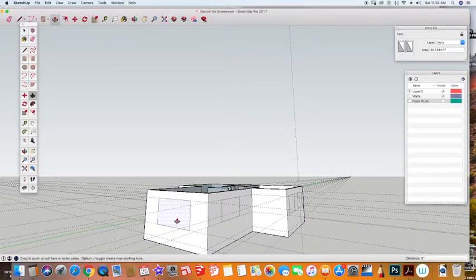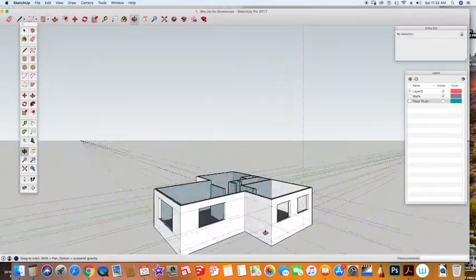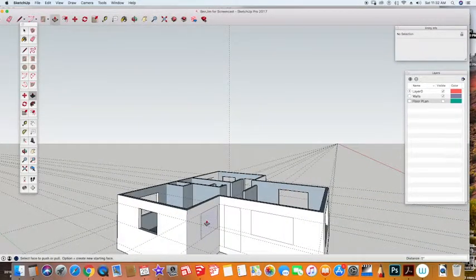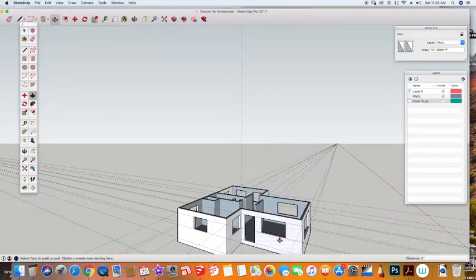So now we're going to push and pull these all in. I'm going to highlight, use the push-pull tool, highlight over it, start to push it in, and instead of pushing it all the way through, I'd like you to type the actual wall thickness, 6 inches. And once you've typed that in, SketchUp will remember it, and you can mouse around to all your windows and just double click that to make the openings for all of your windows. And there you have it.